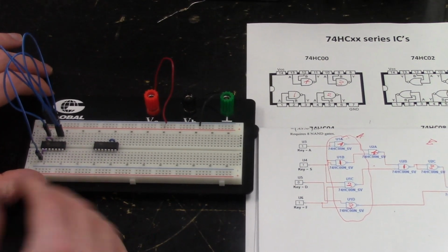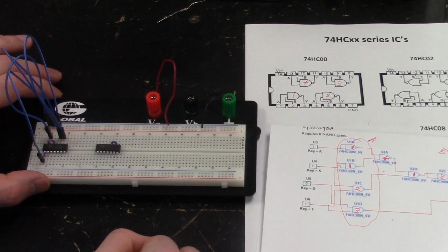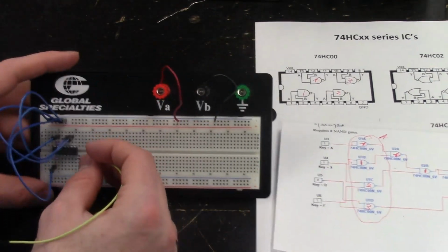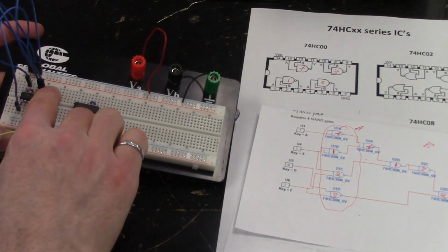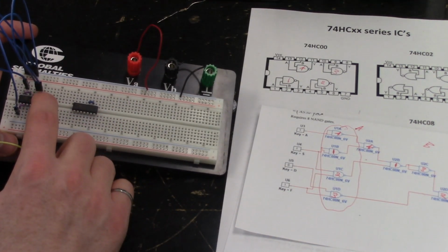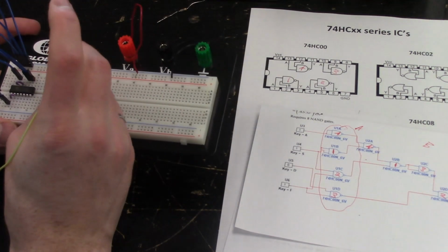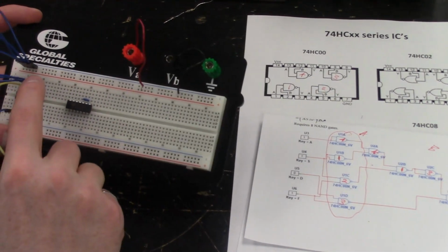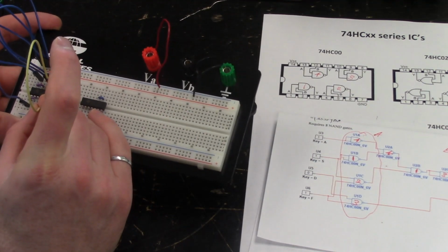So the next thing that we're going to be doing is creating all of the intermediate wires to jump this logic across. So now let's create... let's use yellows maybe for jumping these inputs to different spots. So we need F, which is this 4th one, to not just go to the input to 3, but to also be connected to the input of 2. So that's going to be from there. So we'll go on the input F spot over there to the input of 2, which is number 5, let's say.